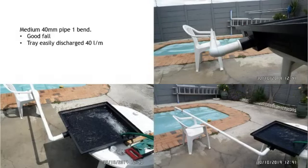40 mil, one bend. Good fall. Check that fall. Straight from the get-go, there's a fall. The length of the pipe, I must admit, in retrospect, I see from these pictures, it looks like it's almost not such a lack of fall, but there must have been a significant or sufficient fall, because on this occasion, you can see that the tray easily discharged the 40 liters a minute.